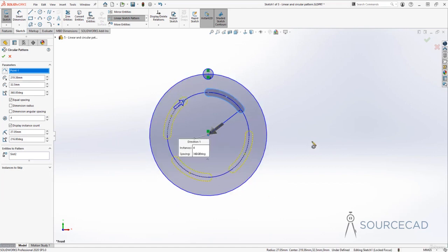Now let's see the number of objects, which is 4. That's 4 objects. I'll make it 5. And you can see this 6. There we have it. So I'll just keep it at 5. And with that, we'll just click OK. But before we do that, how about now checking this option, which is the fill angle. So currently your object is filling the complete 360 degree circle. But if you don't want that, then select this and fill it maybe along 180 degrees only and press Tab key. Now it is filling your objects along the semicircular path only.